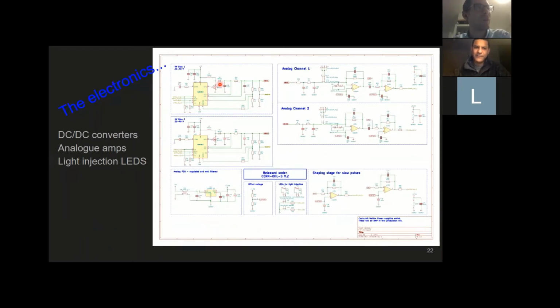And on here, we have a high voltage bias supply. So we're currently using the MAX 1932, which is an SPI addressable step-up converter. It's 8-bit, and this means that we can digitally set our voltage, and it's compensated. So this gives us full control from software over what voltage we put on our SiPM sensor, and it means we can adjust that as part of the calibration process to get a nice balance between gain and noise, enough gain and not too much noise.